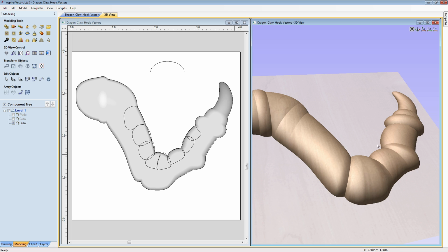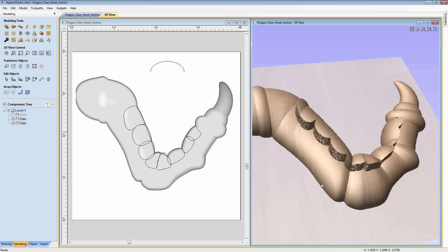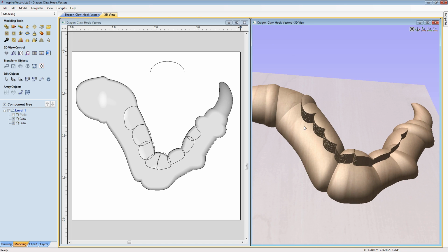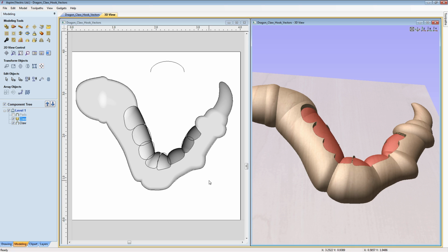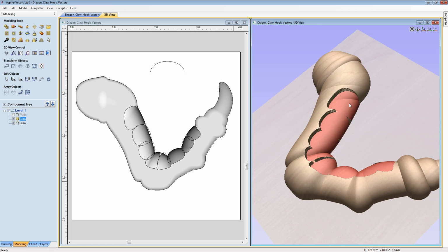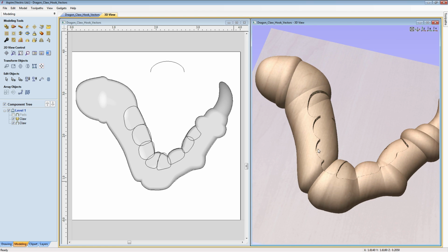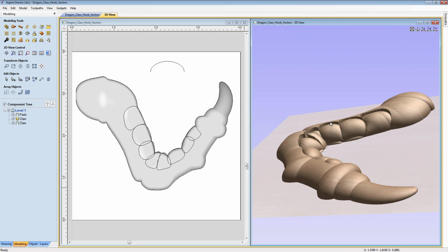I'm going to switch back on the higher claw here, and what I want to do is just make it so that I can only see in these portions where the lowered claw is, and to do that we use an unusual combine mode, or one that doesn't get used very often. There you can see these are being set to add, which is not what I want. I'm going to right mouse click and change the combine mode to low, and what that will do is take those two overlapping shapes and just keep the lowest out of each one. So you can see that now I've got that kind of lowered platform, and when I switch those pads on again, they're being added onto there.